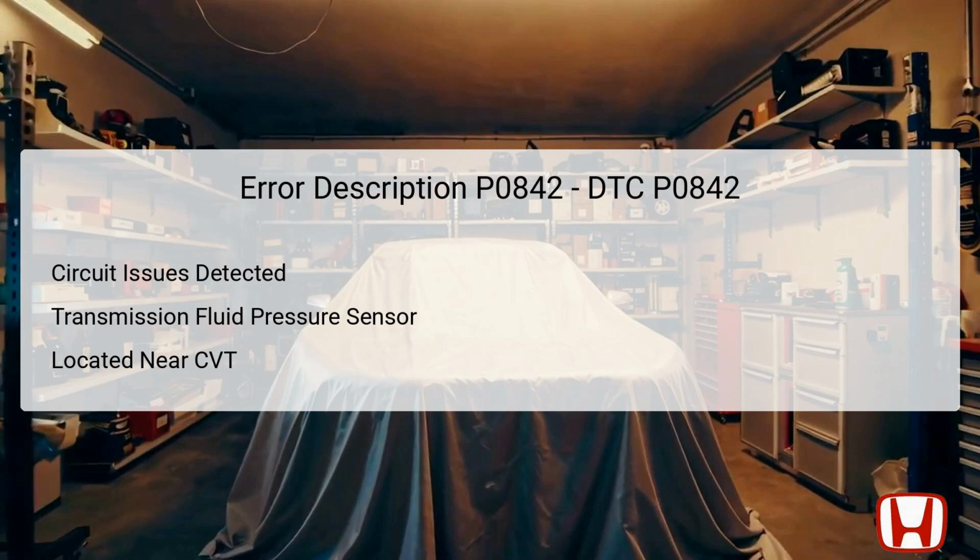The sensor monitors hydraulic pressure to help the TCM manage the correct lubrication and cooling of the transmission components. If the sensor fails or the circuit experiences an issue, such as a short or open wiring condition, the readings will fall outside the normal parameters.